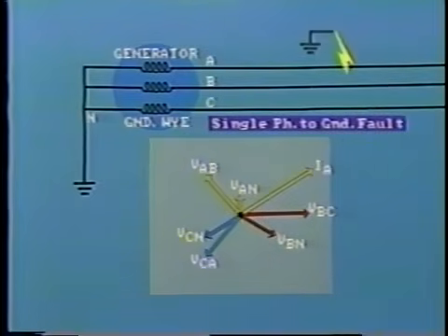With a single phase to ground fault, the voltage of the faulted line to ground will fall close to zero at the fault location, and heavy fault current will circulate through this line and return through the earth to the grounded neutral. The resistance of the fault itself plays an important part in determining the value of fault current. Indeed, if this is very high, there may be insufficient fault current flowing to operate the relays.